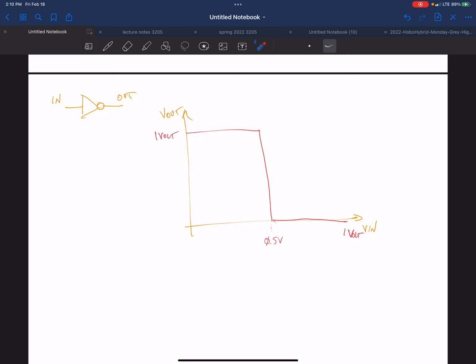And you're always driving the gate of MOS transistors, which are capacitive. You're always using your full power supply, which is really nice, you're just utilizing it. Again, remember, the other thing to remember is power is equal to V times I. So I want to keep that voltage as low as possible, but no lower. And if I'm using it, it's costing me power, so I want to use all of it. I don't want to throw away any of it. Okay?